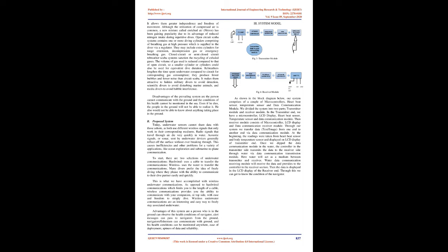Rebreathers lengthen the time spent underwater compared to open circuit for corresponding gas consumption, and they produce fewer bubbles and less noise than open-circuit scuba. It makes them attractive to covert military divers to avoid detection, scientific divers to avoid disturbing marine animals, and media divers to avoid bubble interference. Disadvantages of the existing system are that the person cannot communicate with the ground and the conditions of his health cannot be monitored in the sea. Even if he dies, the people on the ground will not be able to realize it.